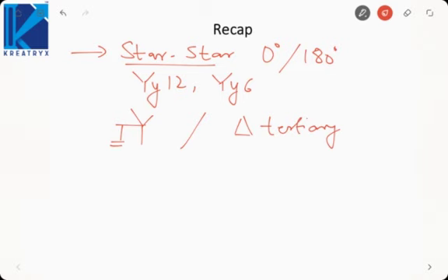The problem with the third harmonic was that third harmonic causes the floating neutral, due to which single phase load could not be connected across a star-star transformer because the neutral was oscillating or floating. Then we covered the delta star connection.